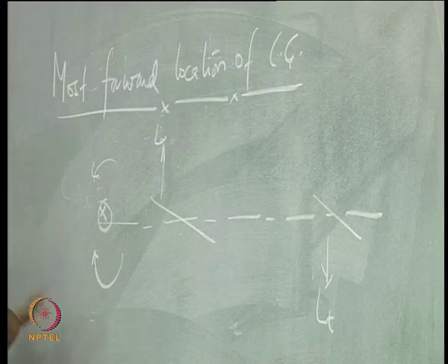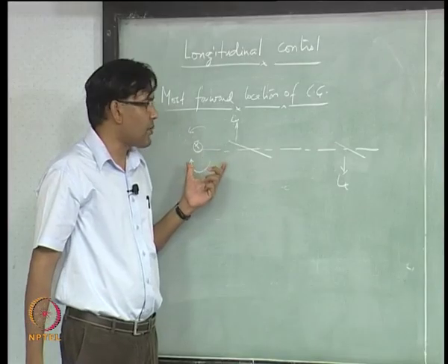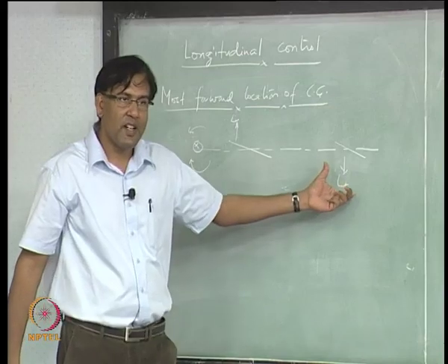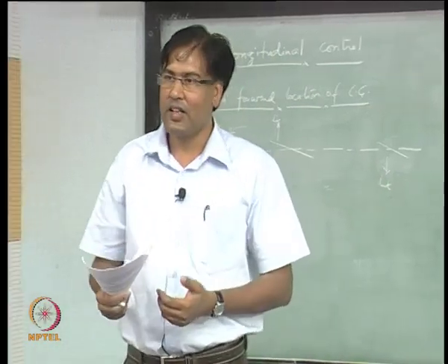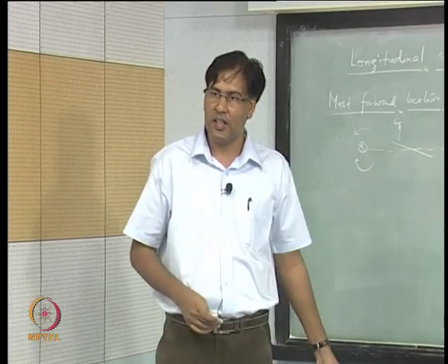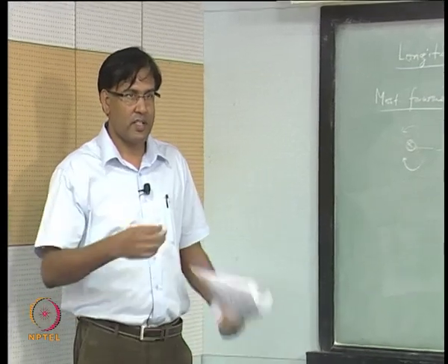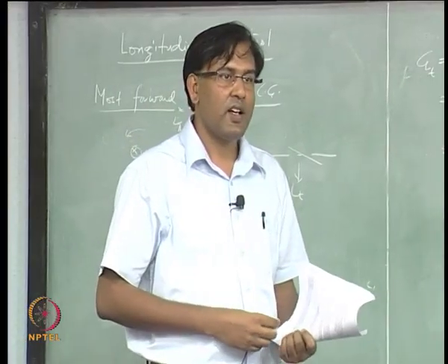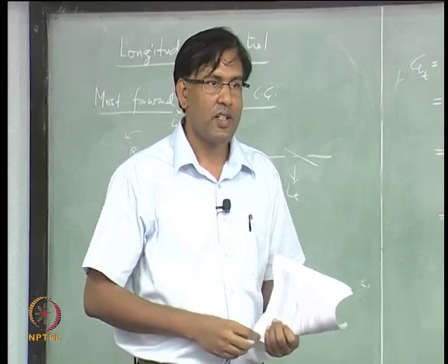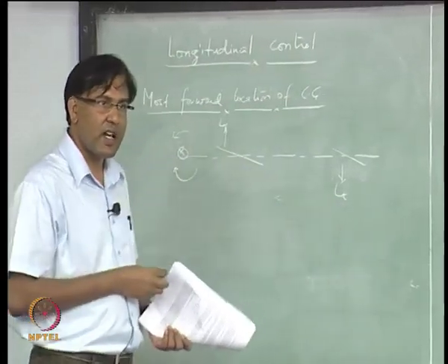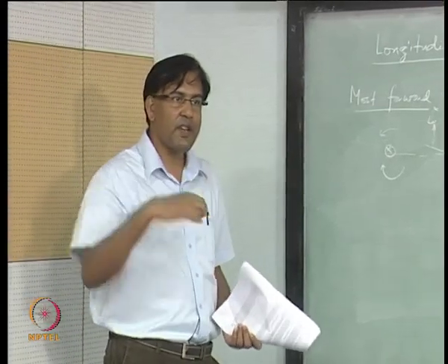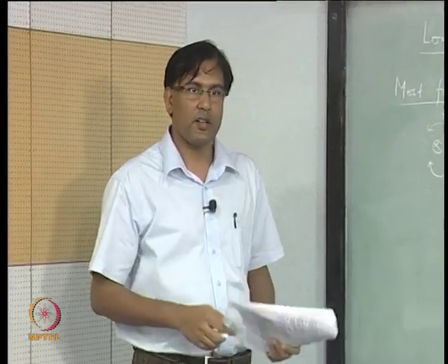What will it depend upon? It will depend upon the maximum elevator deflection, maximum positive elevator or elevator up deflection. You cannot just keep on increasing it. After some point there will be stall, separation of flow, and the lift will start decreasing. So that is the delta E max that you can get.